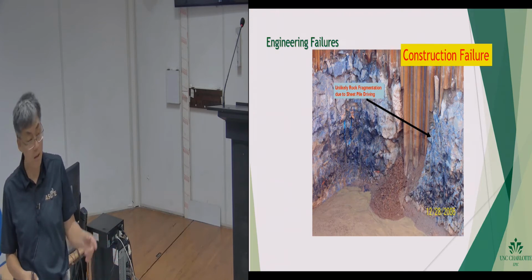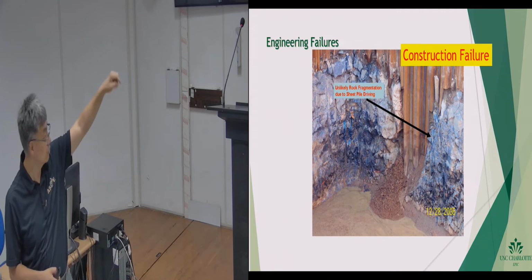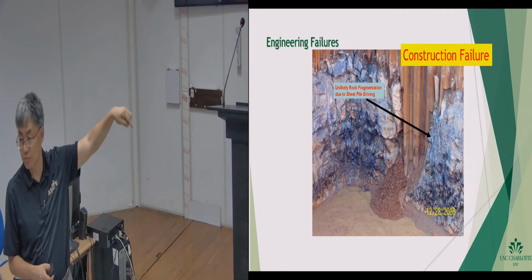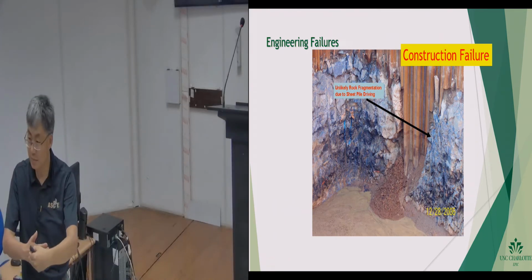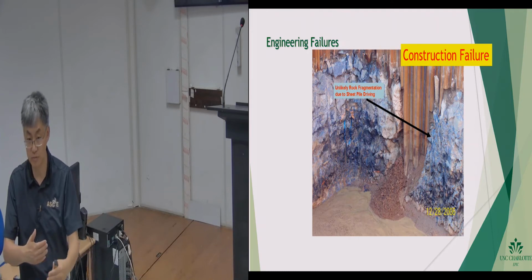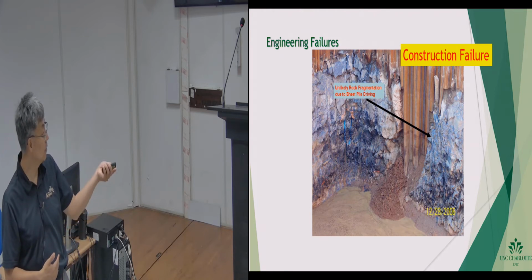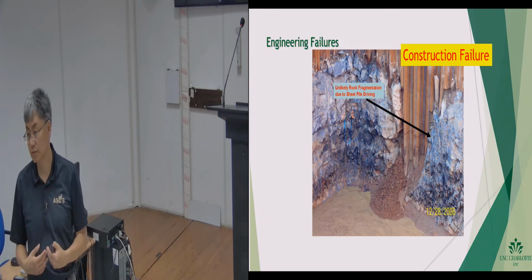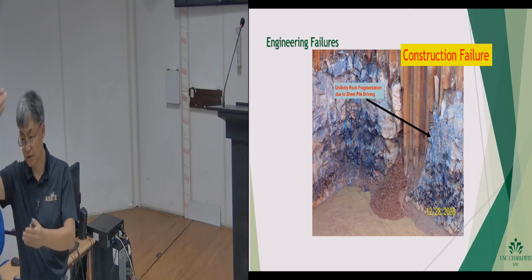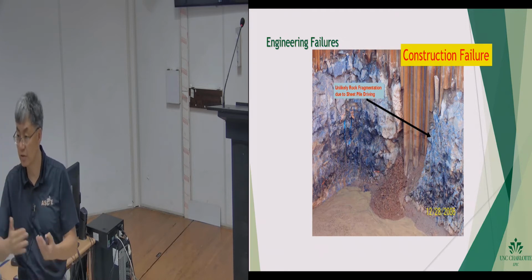It's okay, but when you are doing drilling and then you put in the piles, suddenly behind the piles you have residual soil that you should have excavated completely, and you did not. As a result, when the groundwater starts to flood the area, this material is suddenly washed out, and then the piles become weak, and then you get more problems.